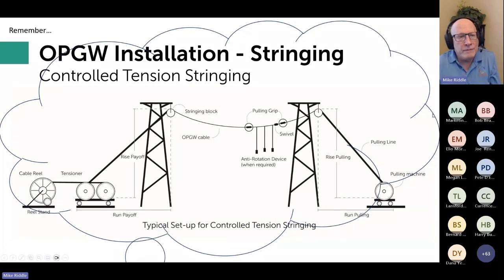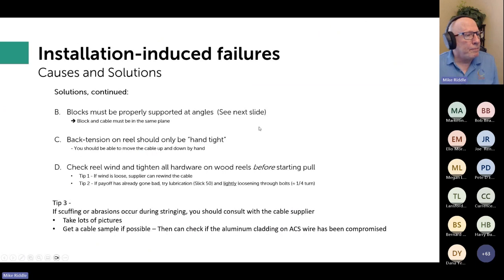So it's just another way of underscoring the point. Pay attention to your stringing blocks. They're critical to your success. So, other things I talked about: blocks need to be in the same plane. I'll show you that on the next slide. We've talked about the cable back tension at the reel stand being hand tight.